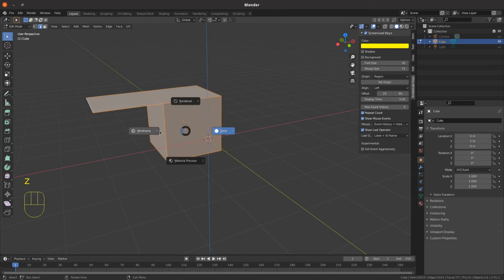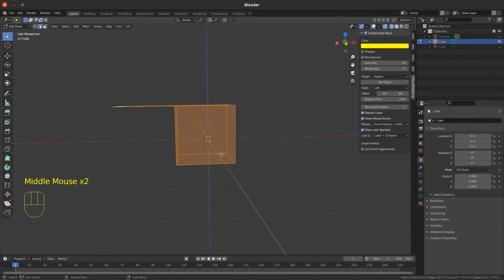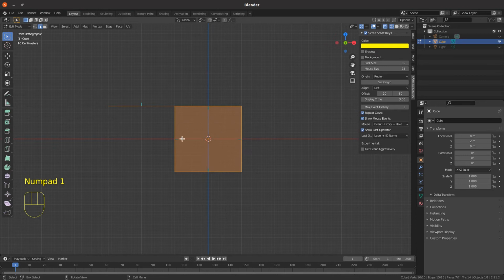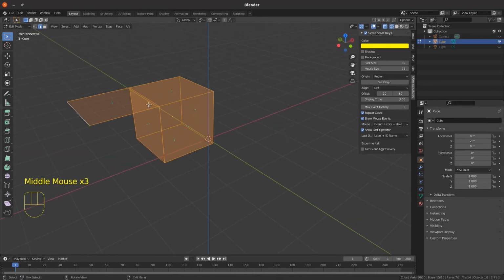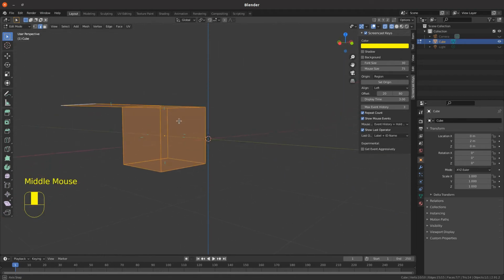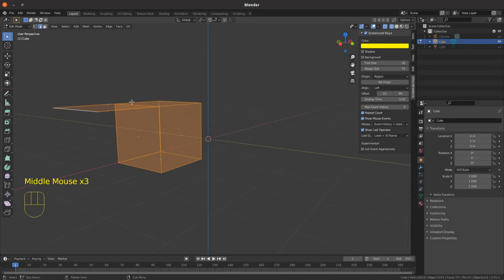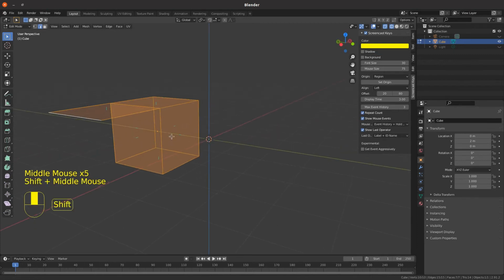Let's just go Z, wireframe. So you can see on this one, just go into view 1. On the box, the face normals are inside out because of the way we extruded it. And this edge normal is pointing in the opposite direction. So that would bring shading errors when the normals aren't facing in a continuous level. And that's because you've got 3 faces coming away from a single edge. So that's something you want to try and avoid in modelling.